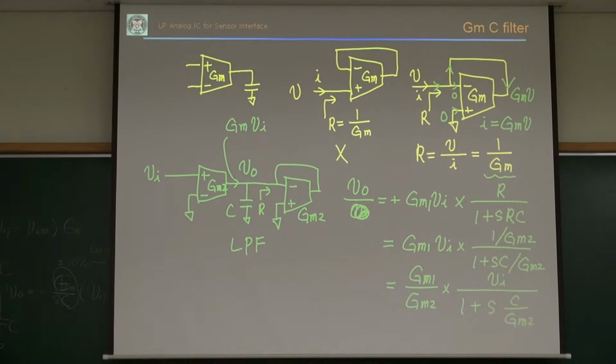Question? Because this is a very simple circuit, there will actually be some parasitic capacitance added here, right? Parasitic cap. We cannot eliminate the parasitic cap. In some very high-speed circuits, they use the parasitic capacitance for this C. Mostly they use a MOS cap here, this capacitor, MOS cap. Then they have matching, okay? Any question? No?